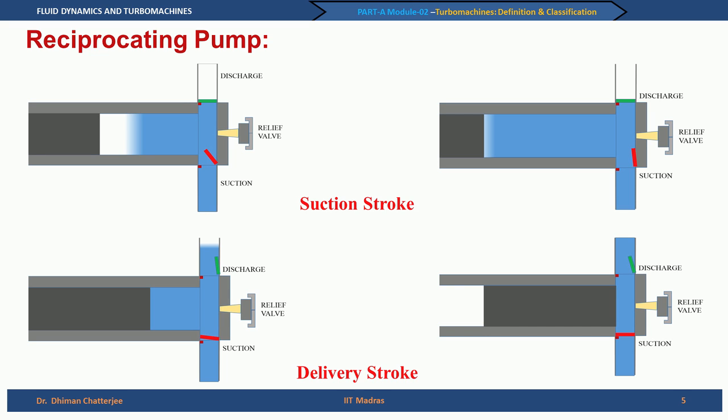The other thing that you have to keep in mind is that because of the presence of these stoppers, which allow only restricted movement of the valves, there is less chance of leakage, and hence this type of pump is expected to handle higher pressure rise. This makes a very big distinction from that of turbo machines.